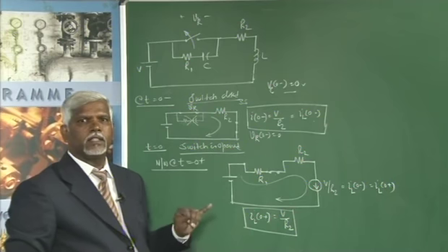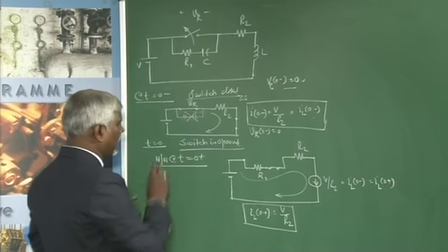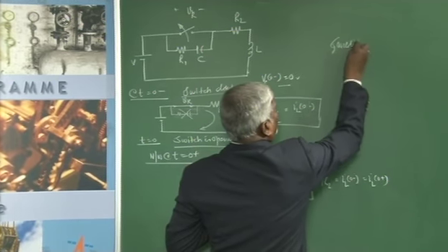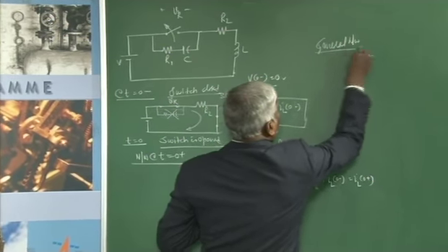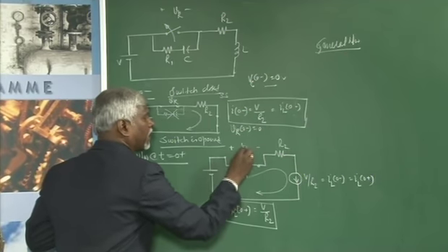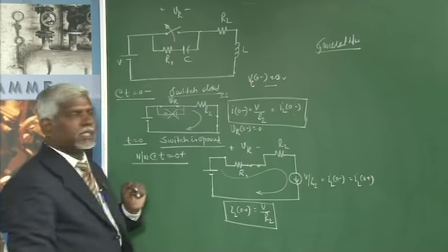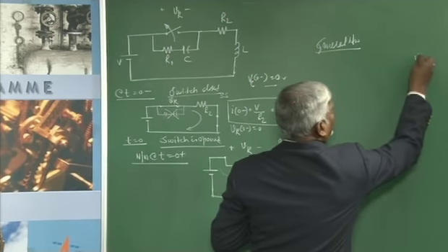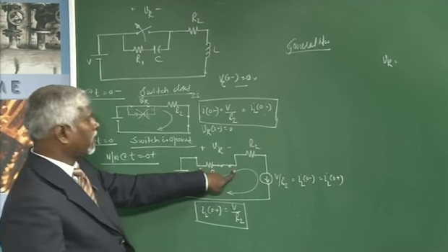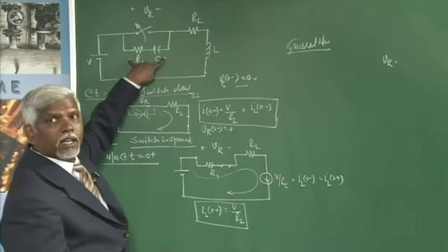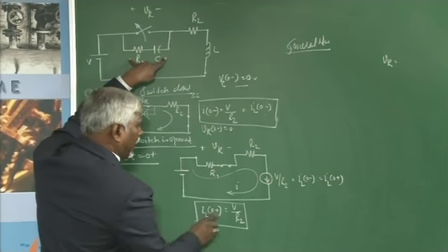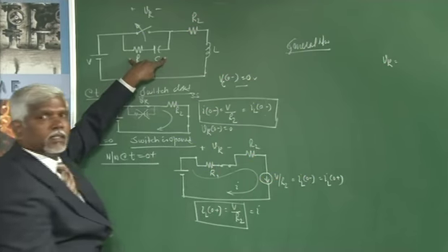Now, we need to write a general network after switching. So, general network after switching, he says what is the voltage across your switch, plus and minus Vk. Please remember this, Vk is equal to the voltage across this combination, the voltage across R1 and C. If I take this current as I, the inductor current IL is nothing but I, the same current.